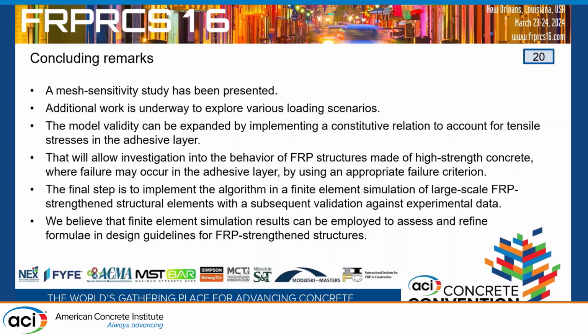and we are now working on exploring the response of the adhesive joint to different loading scenarios, for example varying the step in the quasi-static loading, and also other testing protocols. The model validity can be expanded by implementing a constitutive relationship for normal stresses. This potentially will make it possible to simulate the behavior of high-strength concrete elements reinforced with externally bonded FRP.